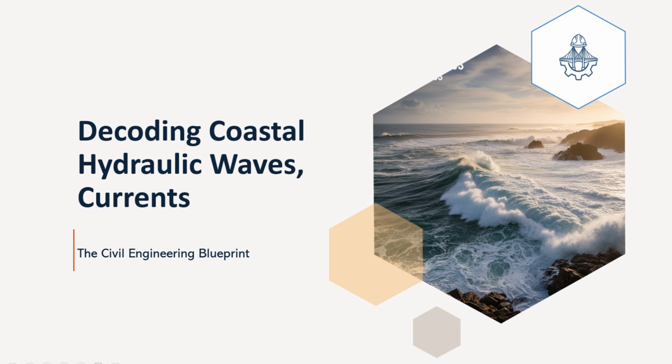Okay, our first key process is wave shoaling. This is what happens as waves move from deep water into progressively shallower areas. They begin to feel the seabed, right? And this interaction fundamentally alters their characteristics. You'll observe several dramatic changes. The wavelength, L, decreases significantly.